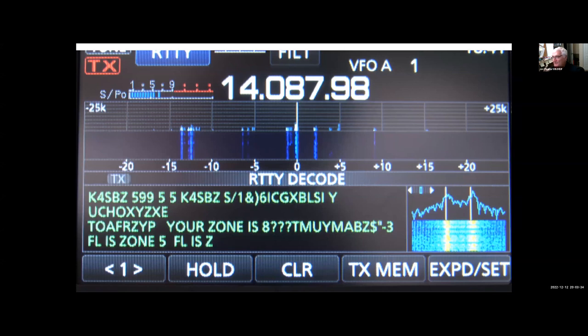It's none of this quadrature amplitude modulation stuff that's part of these more complicated modes, just two little tones. And so you tune it so that the yellow bar and the peaks from the signal are within these lines, and then it'll be decoding that. So that's how you can decode.